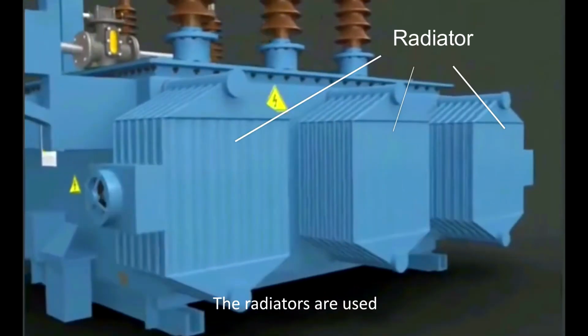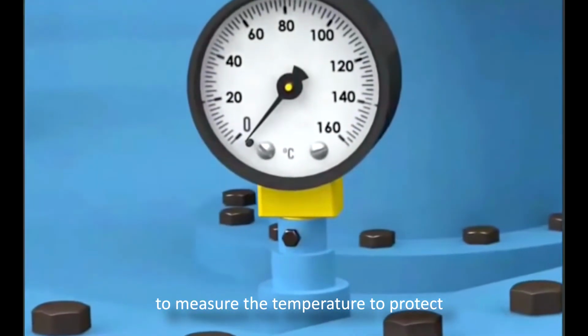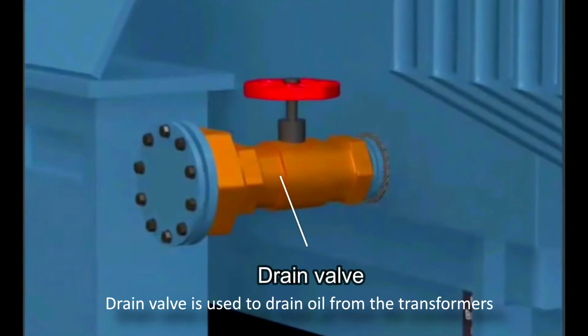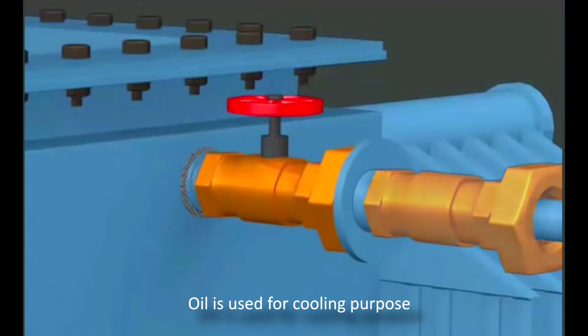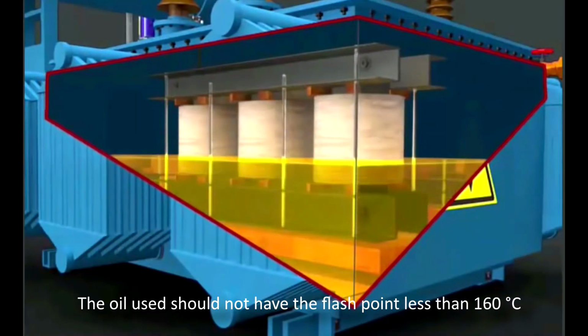The radiators are used for transformer cooling purposes. A thermometer is mounted on the transformer to measure the temperature, to protect against the temperature going too high or too low. A drain valve is used to drain oil from the transformer. Oil is used for cooling purposes. The oil used should not have a flash point less than 160 degrees Celsius.